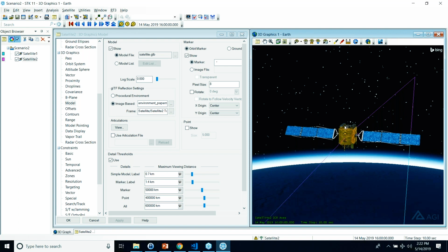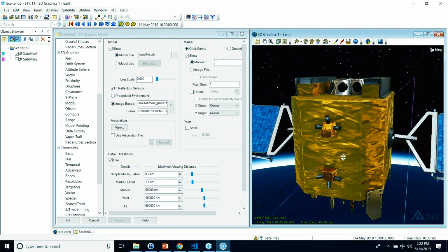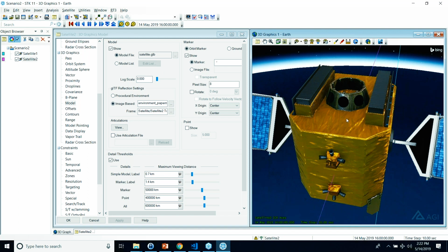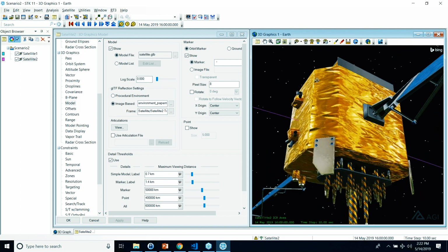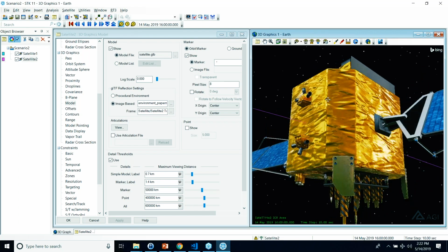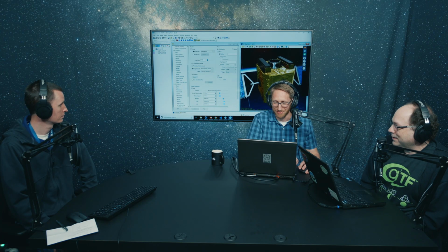The only downside is if they zoom in a little too close to the satellite, you might see a tree branch or something reflected on one of the shinier panels, and then the gig is up. You can realize, wait, those are leaves I'm seeing in the reflection environment, and then people know that you've pulled some dirty tricks on them with the reflection environment. But as long as you keep the gold foil crinkly and you keep the camera a little further away, it can make the satellite look a lot more believable to have an Earth surface type environment wrapped around it. Yes. So long as it looks good.